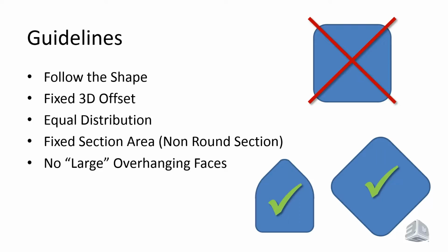When you think about the process of printing the core, basically, we're layering layer upon layer, one upon another, as we build up the steel on both sides of that water line. Well, what sits in between here is just powder. So as we get to the top, all we have to support the top when we lay that last layer across that closes the top of the water line is powder, and that's not enough. We're trying to stretch this all the way across with no support. Okay, so that's what we call an overhanging face. It's sticking out over a void with nothing but powder in it. What's there to support it? All right, that's an important thing to realize about the printing process.